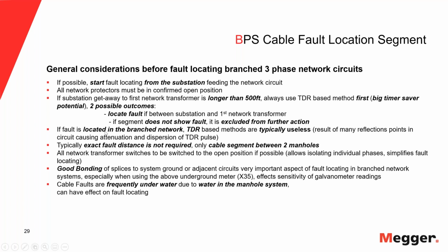One other point that's really very important and sometimes gets a little forgotten is the bonding in these network circuits. In the old days, in every manhole where you had a splice, you had a grounding rod, everything was bonded, was perfect. Today, in many cases, there are no grounding rods anymore in the manholes, or they're abandoned or not replaced because they're so old. But why is bonding important?